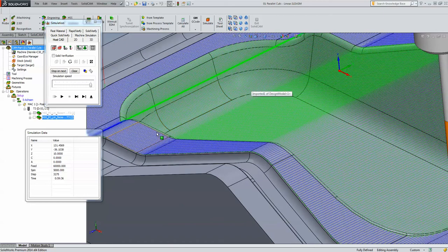Okay, now, while I'm here already, let me talk a little bit about this area. I want to make a little bit of a change. Now, you note that it went directly from one side to the next over here. Now, instead of doing that, what I'd like it to do before it goes directly to the next side, when it relieves this surface, I'd like it to actually leave with an arc going up, and then go across to the other side, and then lead in with an arc going down into that area over there, instead of going directly into that surface.